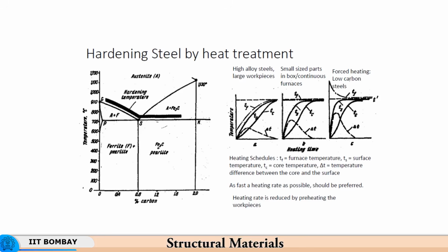If it is very rapid, then there is a risk of cracking at the surface, because the surface would expand much faster than the interior, and significant tensile stresses would get set up during the course of heating.